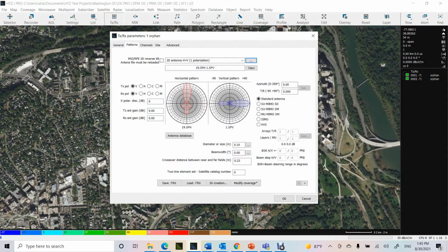And then as you see now, I have the panel antenna, which I can point into different directions. So you see that we have azimuth that you can select, and we have the tilt that you can use for your vertical. For our case, let me just put it on 0, and I would like to introduce you to our comprehensive MIMO antenna, and then I will show you how you can use our beamforming option as well.